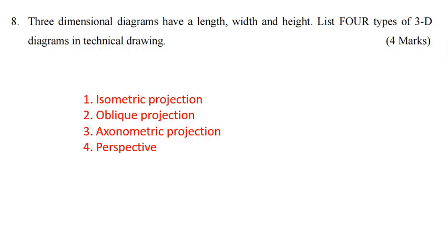30 by 30. Then the second one is oblique, and in oblique we have 90 degrees by 45 degrees. 90 degrees or 45. Some people like to call it 0 degrees by 45. So one side of oblique is lifted at 45 and the other one stays placed on the baseline. Then we have the axonometric projection, which has an angle of 60 by 60.